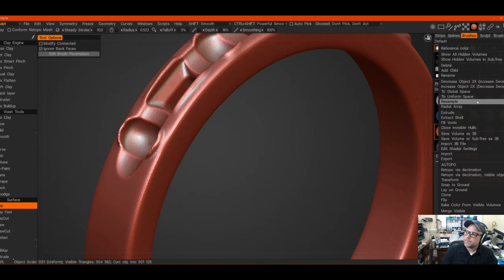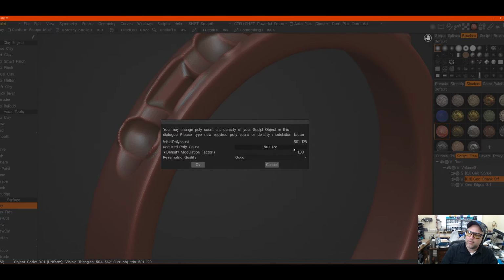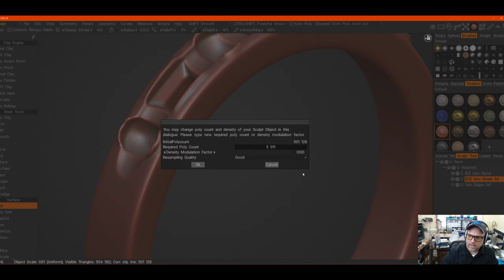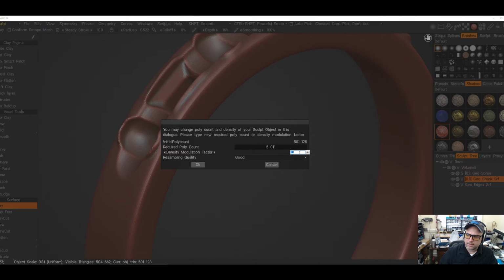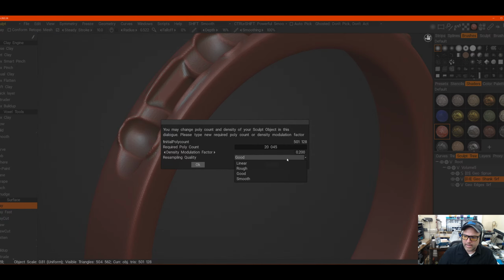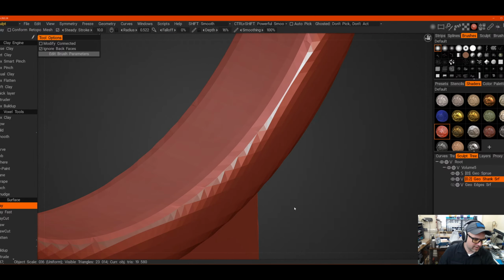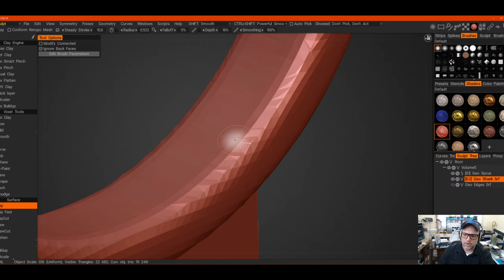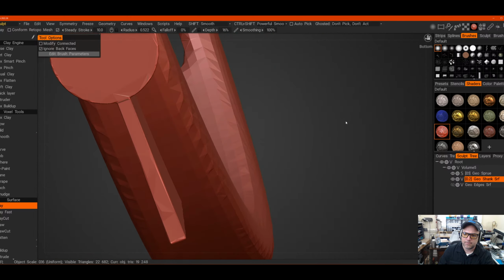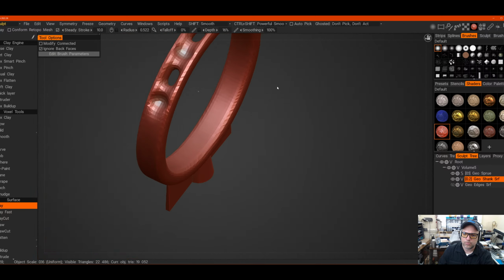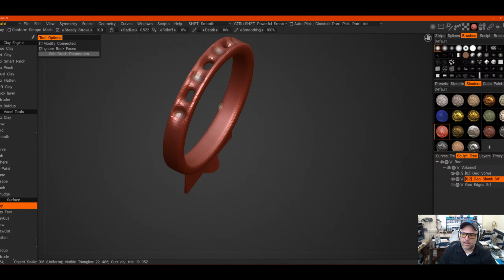You resample this down to like 0.1. Okay. That may be too much. 0.2. Okay. And smooth and tell it okay. And you just hit Control R, SmoothAll one time, and it will take that sharp edge and give you the best little fillet possible. It's just going to round over those edges real quick, real fast.